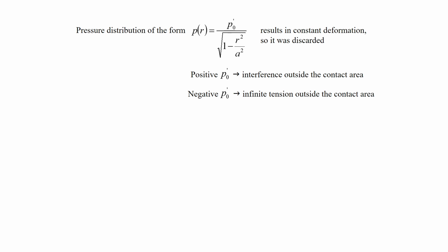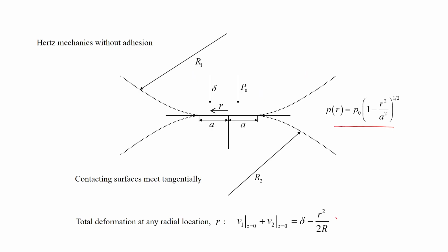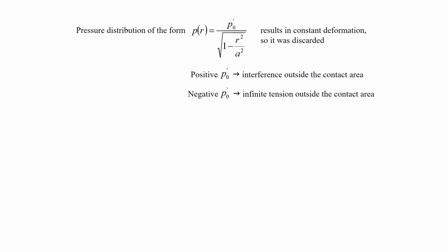Now, when you consider this Hertz pressure distribution or the contact of these two spheres, we did not consider, remember, this particular kind of pressure distribution. This particular pressure distribution is observed when we have an elastic half space and a flat punch like this. Remember that when you have a flat punch and we apply a load on it, let us say some load P dash, then this elastic half space deforms like that. It happens something like this.